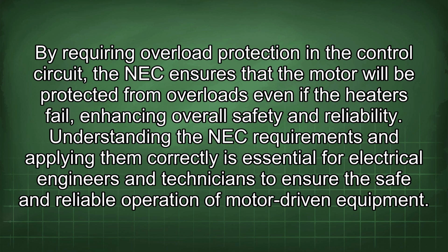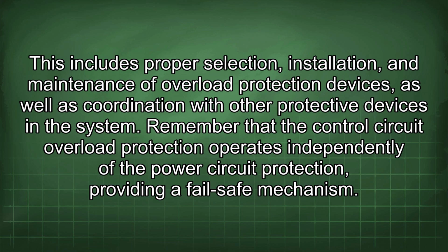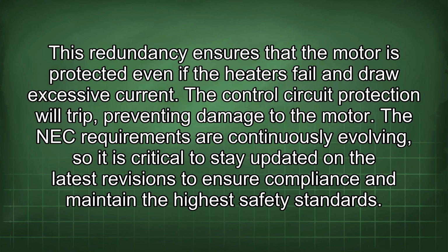Understanding the NEC requirements and applying them correctly is essential for electrical engineers and technicians to ensure the safe and reliable operation of motor-driven equipment. This includes proper selection, installation, and maintenance of overload protection devices, as well as coordination with other protective devices in the system. Remember that the control circuit overload protection operates independently of the power circuit protection, providing a fail-safe mechanism. This redundancy ensures that the motor is protected even if the heaters fail and draw excessive current. The control circuit protection will trip, preventing damage to the motor.